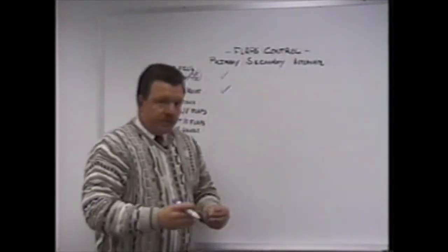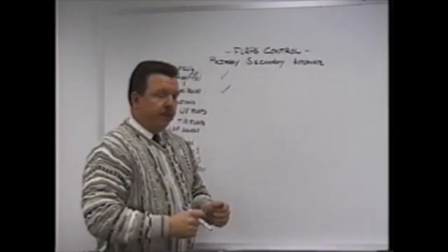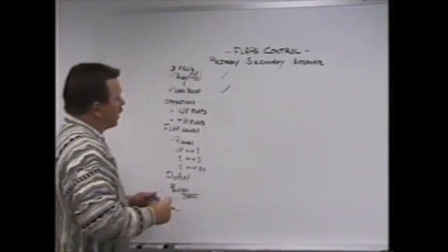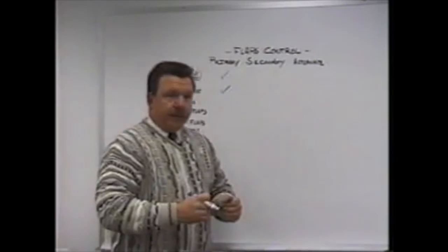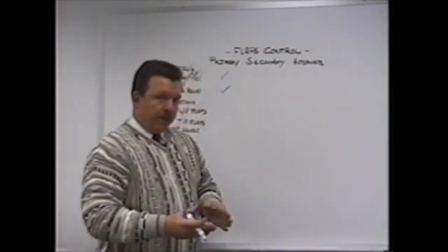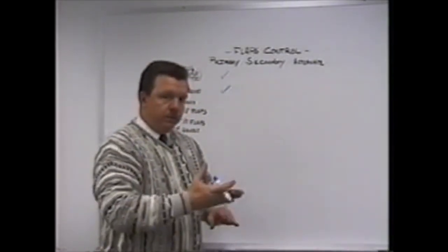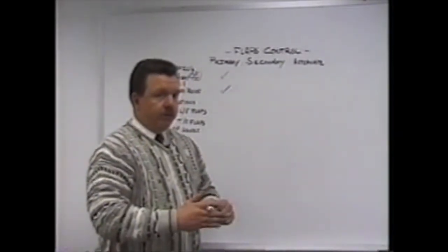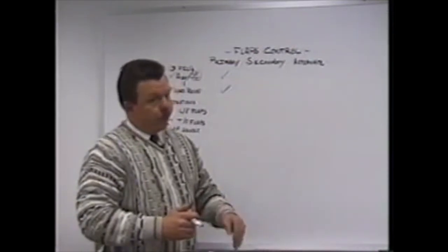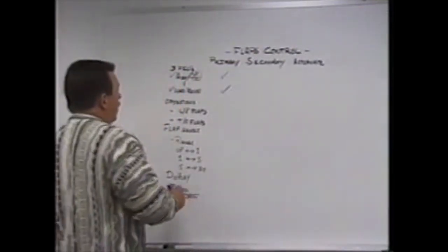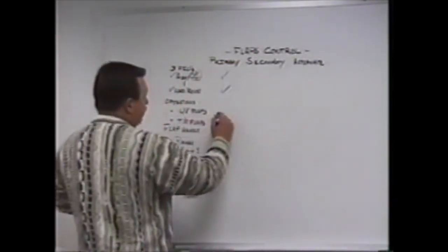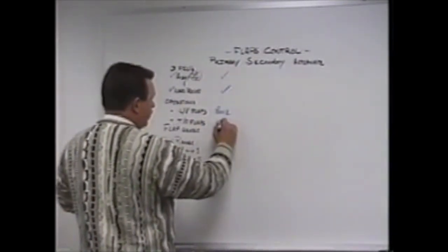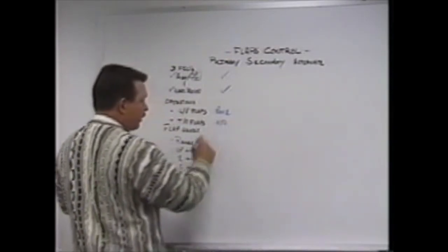Load relief. When you select flaps 30, and if you overspeed flaps 30, the trailing edge flaps will blow up to position 25. If you select flaps 25 and you overspeed them at 25, the trailing edge flaps will load relief to 20. So 30 to 25 and 25 to 20 is load relief. If you overspeed them at flaps 20, they deplane. As far as the operations go, leading edge flaps, again, were pneumatic operation. Trailing edge flaps were hydraulic operations, systems 1 and 4.